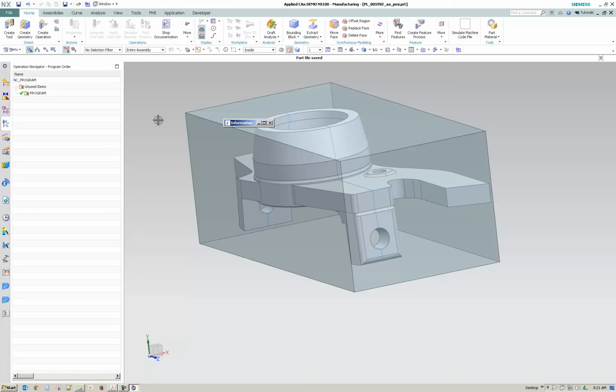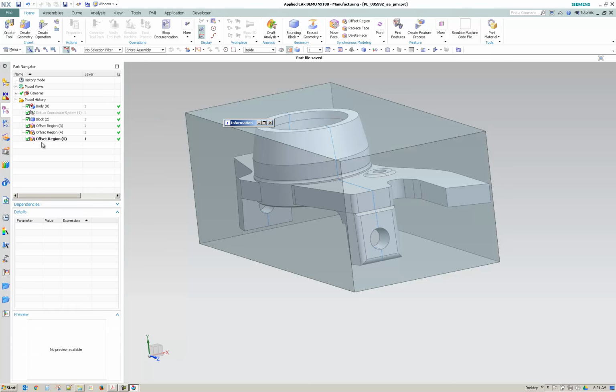And so now to create the assembly where we can modify or move the location of the part relative to an assembly, this allows it. If you were to move the part inside of this part file, you're moving the actual body relative to the way it was designed. And so if you were to import a new revision, you would have to move again. By creating an assembly and moving the part around, we haven't moved the body relative to itself. So if there's a new revision, you can bring in a new revision and you won't have any relocating to do.